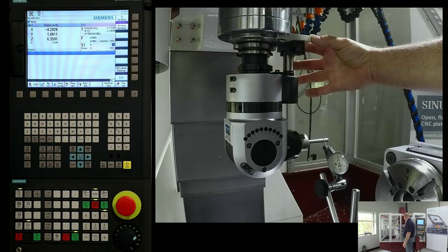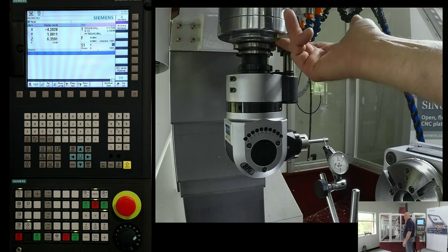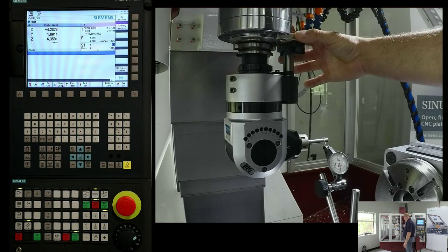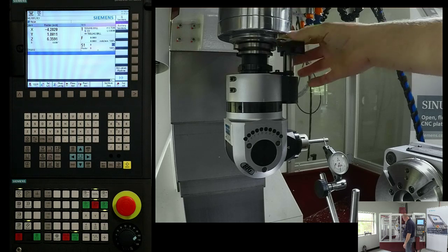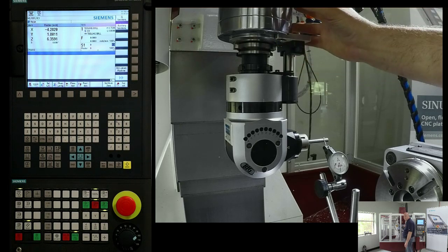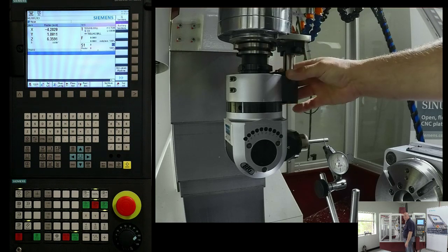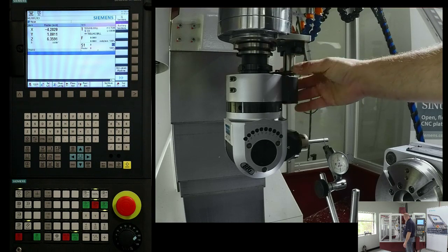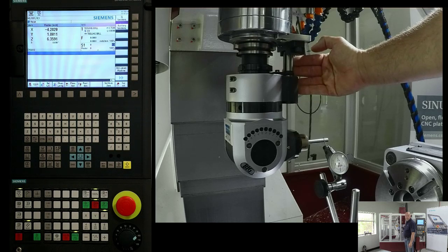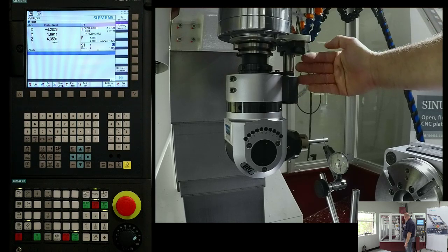So I made this block that located off of some bolt hole patterns on my spindle cartridge. Pretty common way to mount these, or you can make an extending block off the spindle flange or come off the head. But I need to have some way of being able to put this head in and out of the machine and have it locate the same point at all times. So that's what this block is going to allow me to do.